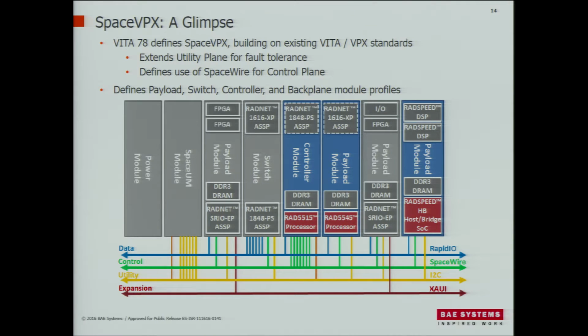So again, this is a real whirlwind. What the heck's Space VPX? So Space VPX is defined by VITA 78. It's an open standard, and it was based on previous VITA standards, based on the VPX and OpenVPX standards. A couple of the main goals, deviations from the existing standards, was fault tolerance on the utility plane.